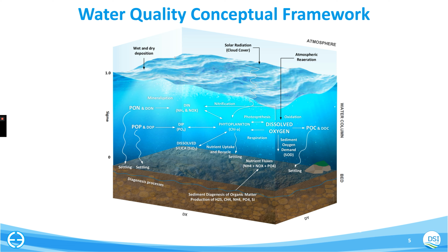There's a lot of parameters, such as the conversion factor between carbon in the algal groups and chlorophyll A. That ratio is somewhat standardized. And we initialize it, but you can change it, of course, if you have site-specific information.